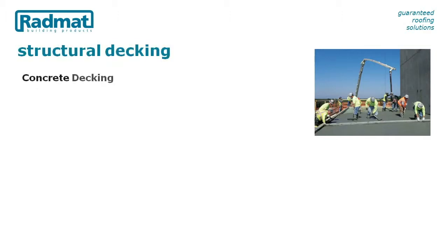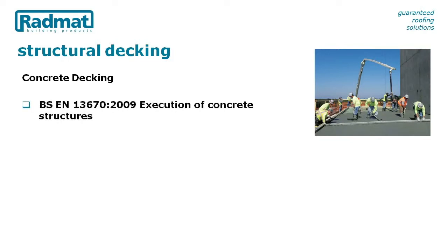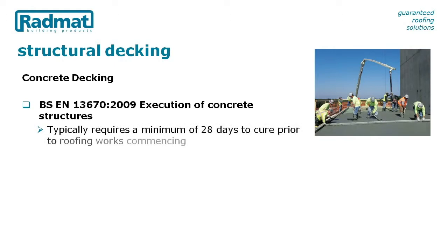Inverted roofing is typically installed on a concrete deck due to the 80 kg per square meter loading required to retain the insulation on the roof. In situ concrete is the easiest to apply to, ideally without a screed to falls, as this can complicate the application and delay the installation program.